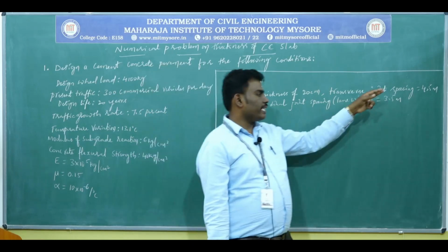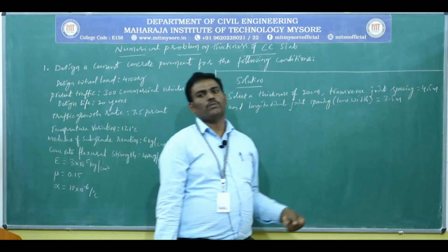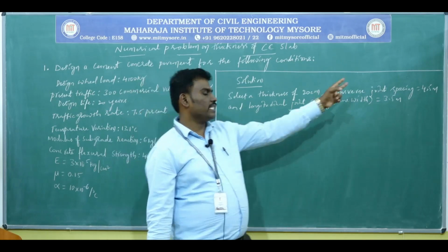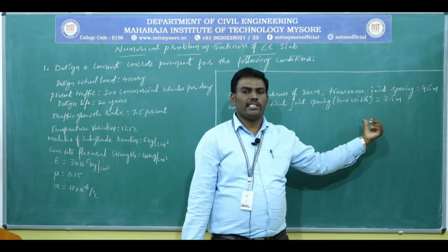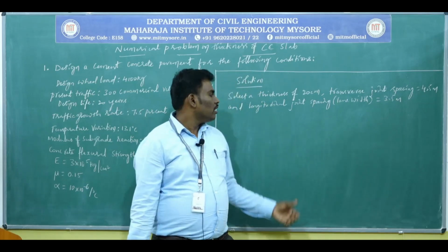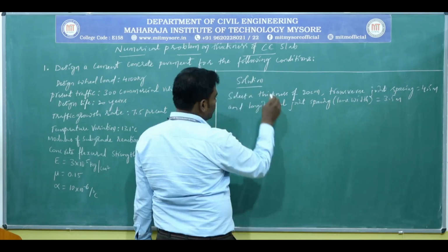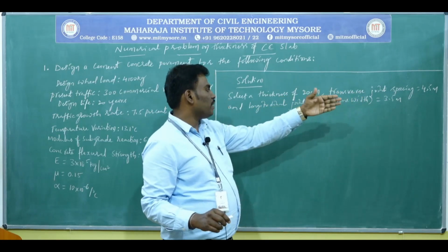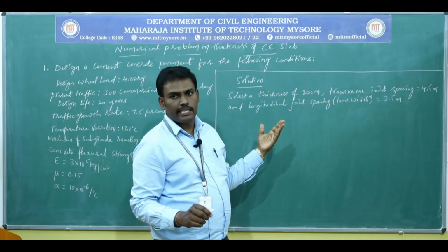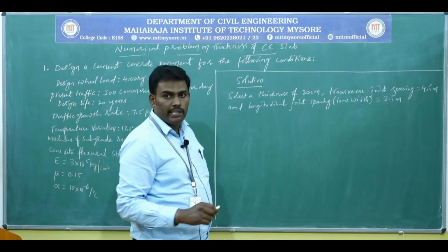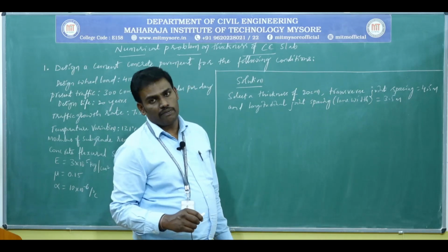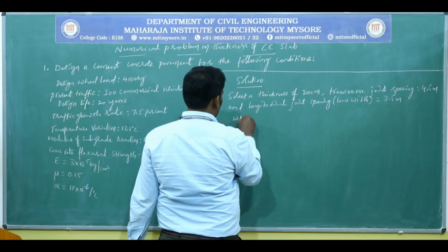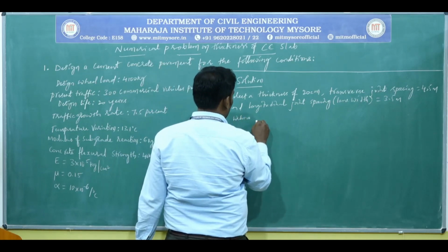Lx, Ly, or we can say L and W. Longitudinal spacing is L and lane width is W or Ly. Once you assume the transverse joint spacing and longitudinal joint spacing and have selected a trial thickness, then you need to find the radius of relative stiffness.